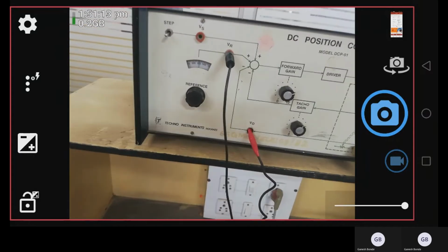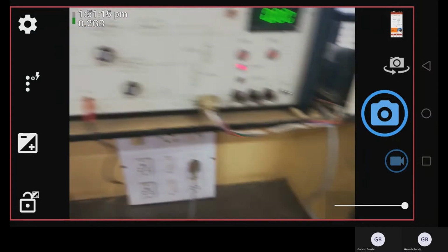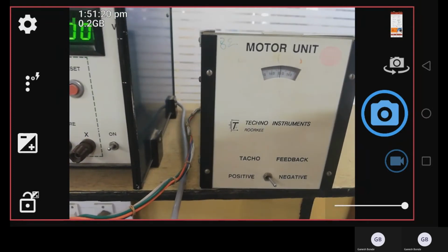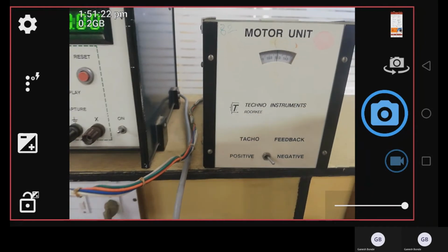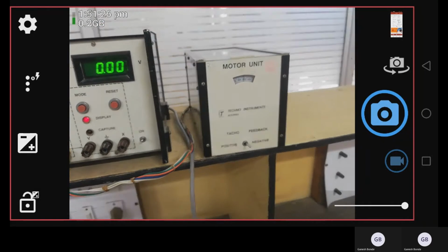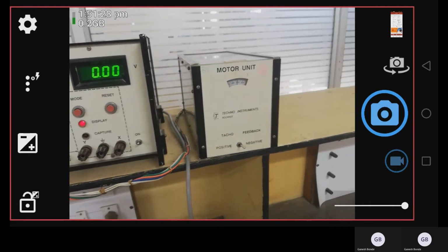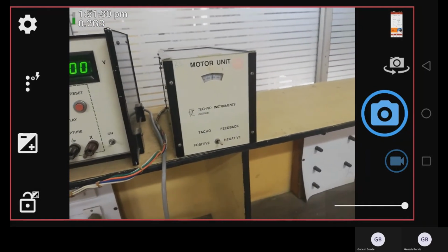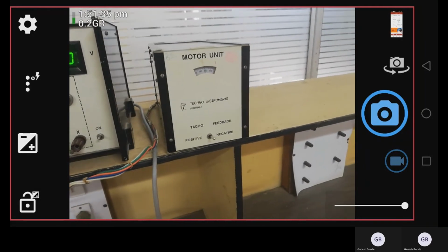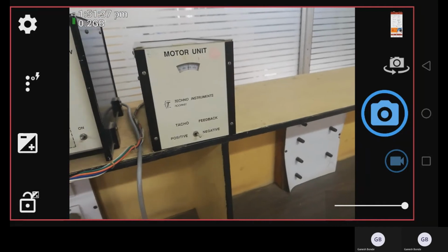You see, as I have changed it to 150, the motor shaft has also changed to 150. So it automatically adjusts. As the reference pot is changed, there is a difference theta r minus theta 0, and according to that, an error signal is provided to the motor, and the motor moves the shaft from 130 to 150.